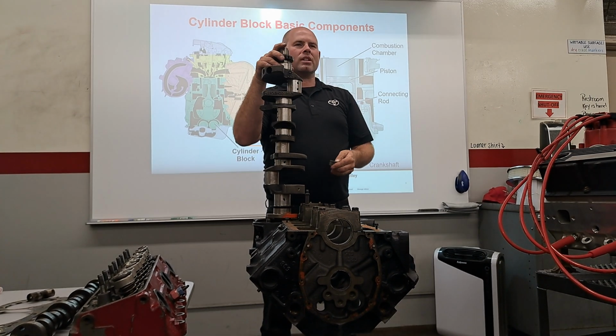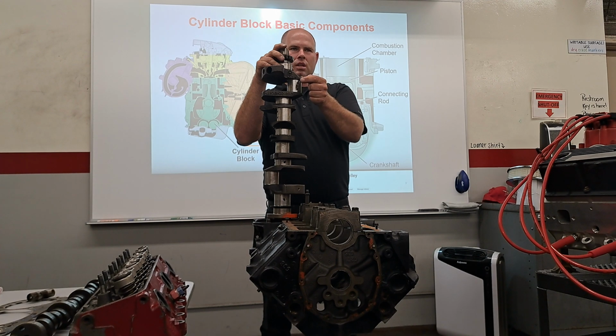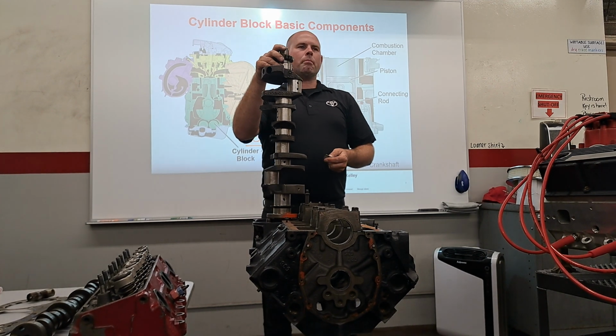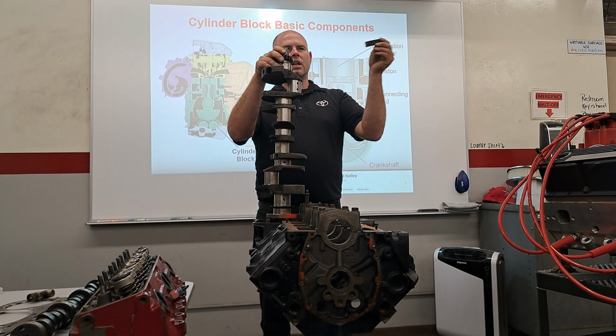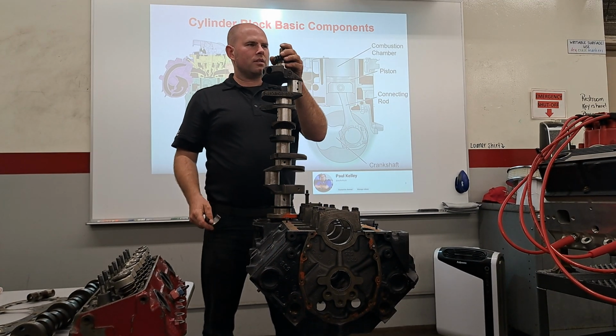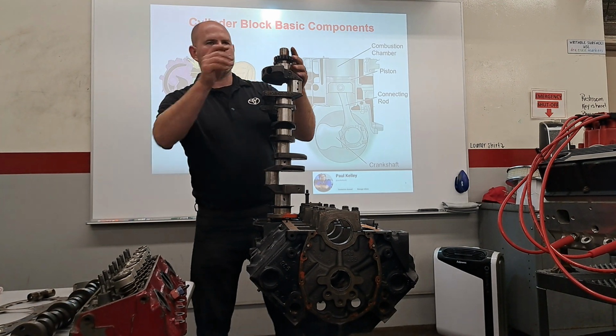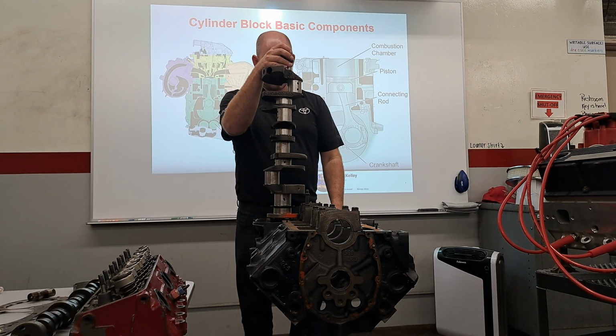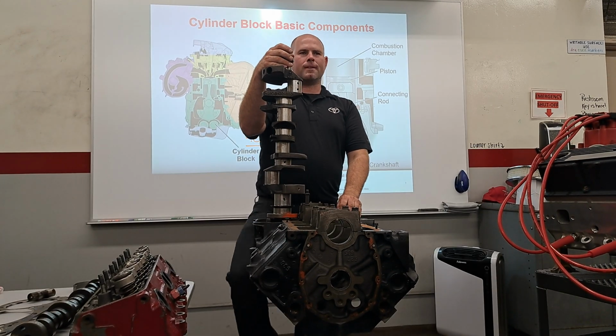So when the combustion's strong, the rods get kind of beat up. I was gonna say, so you would argue that if, let's say, there's a loss of pressure when it comes to oil, the connecting rod bearings will fail first. Yeah, most likely.